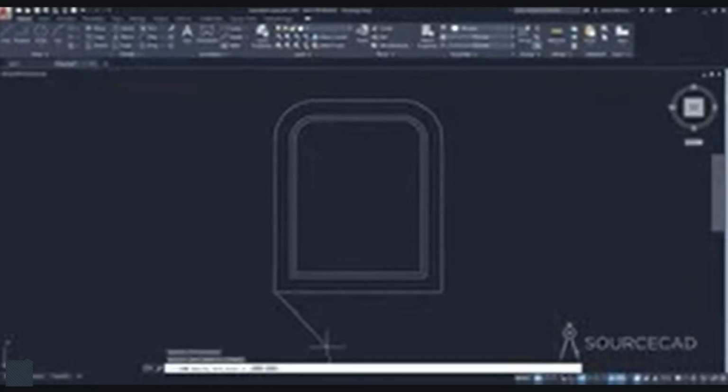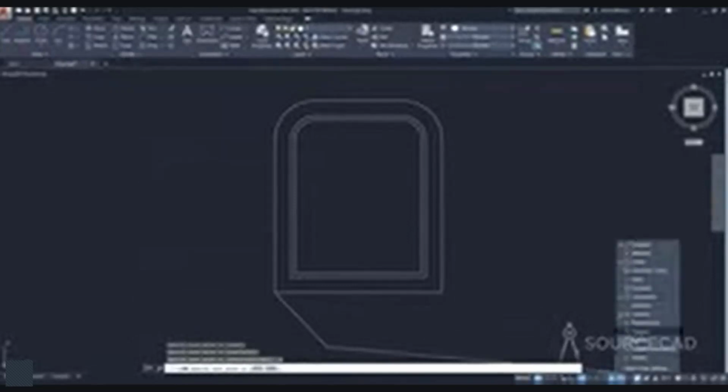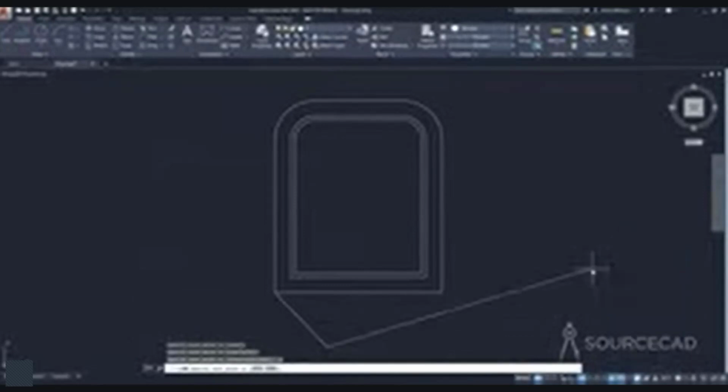And I'll just click here, and now I'll move my cursor close to the midpoint of this line. But look at this, we don't have anything. Now even if I click here, which is very close to the midpoint, look at my drawing. It will snap the line to this point because this was highlighted. It won't snap to midpoint. Now I'll press Ctrl Z and I'll go to this object snap arrow. Okay, see the importance of object snap. Midpoint. Also make sure that this tool is also active here on your status bar.